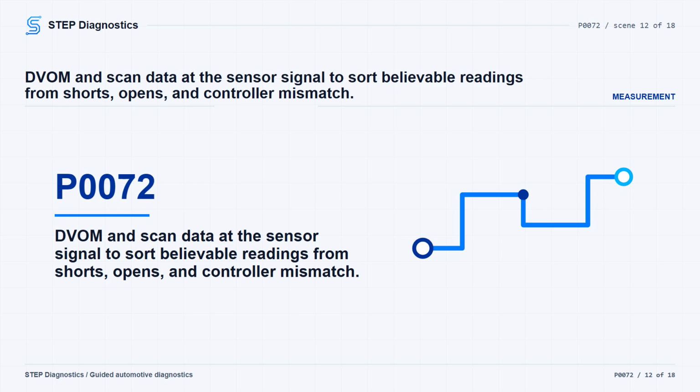If the signal is above 6.0 volts, the signal circuit is shorted to another voltage supply. If the signal is a constant 5.0 volts, think open farther downstream, most likely at the sensor or sensor ground side. If the signal circuit checks good, disconnect the temperature sensor and controller harness connectors. Check the signal circuit for high resistance and short to ground. Then move the test lead over and back, probe the sensor ground circuit at the sensor harness connector.